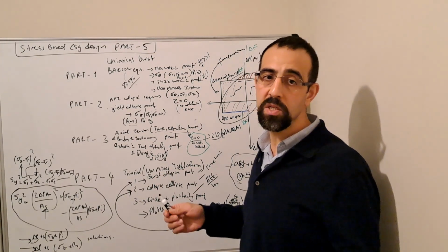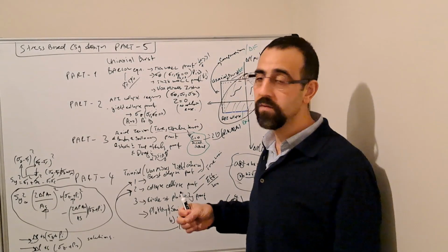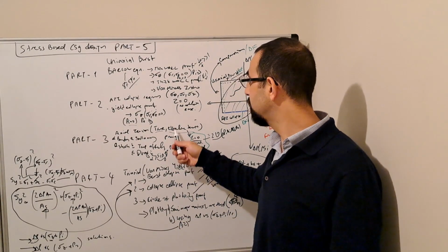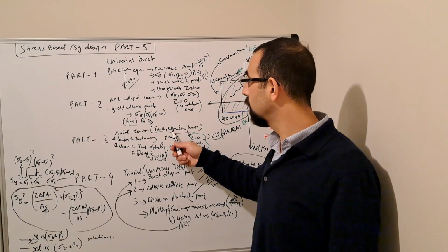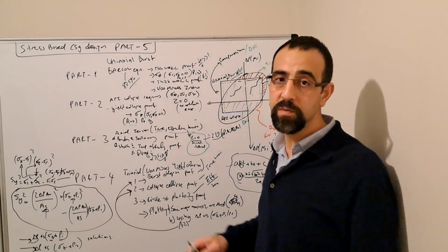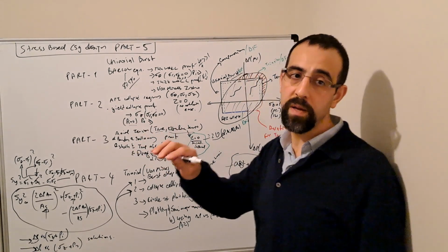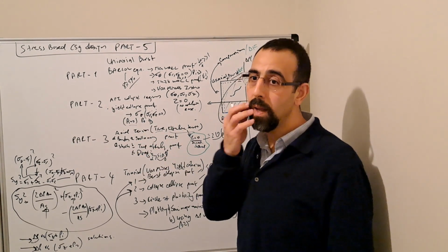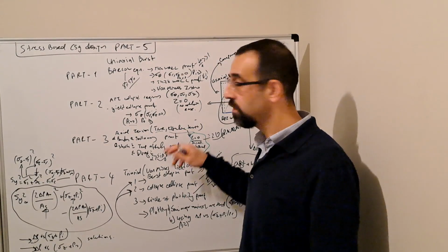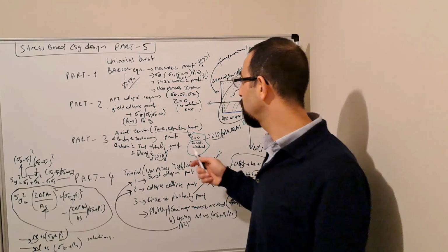So what will be the initial tension profile of the cemented casing? We calculated that it is the result of the difference between the outer area times the outside pressure and the inner area times the inside pressure at the shoe, and the effective tension at the shoe is zero. We have shown that.